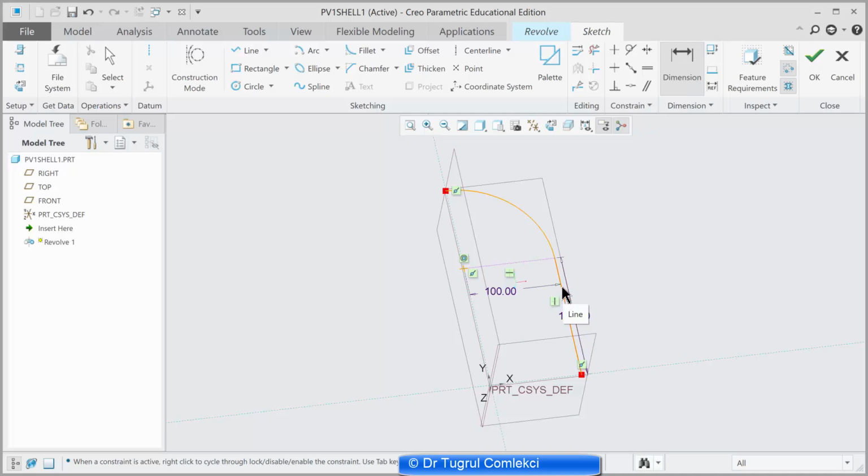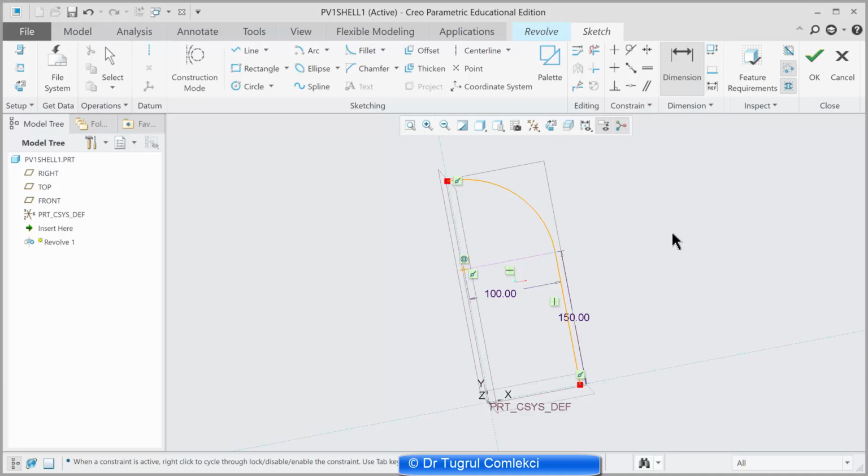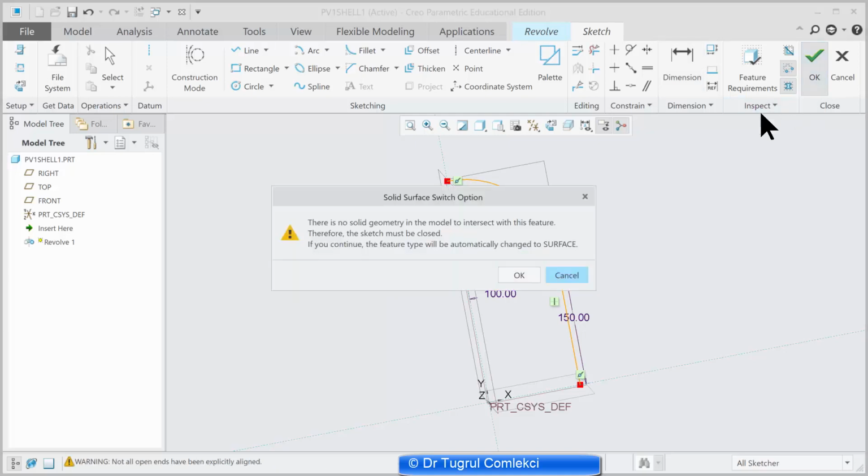So we need to make sure that on top of 100 millimeters we can add half of that thickness. So the thickness value we'll need to define as a parameter, and then we can refine the dimension here. So we can just keep it like this at the moment.